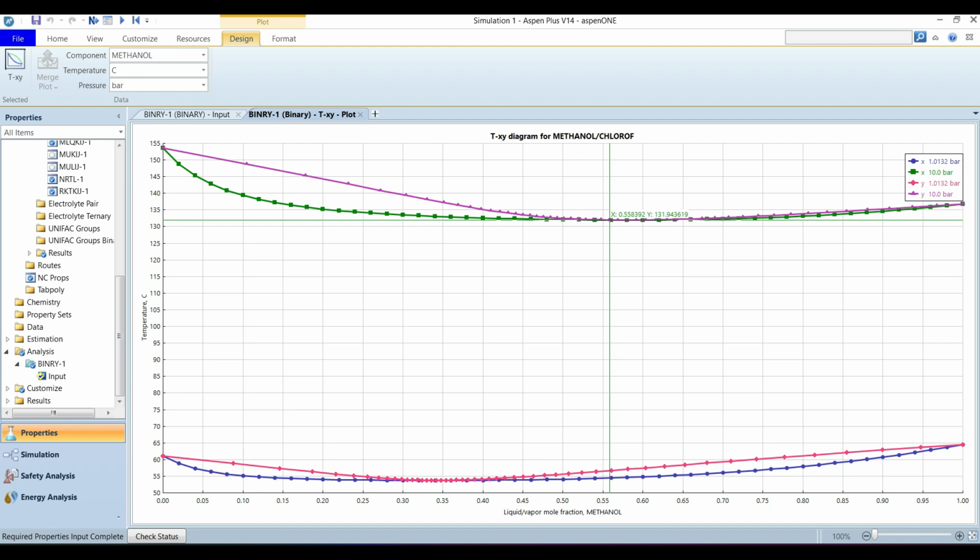So that will be a closed loop between the two columns, first operating at a lower pressure, then generating the pressure to a higher pressure. The second column will be operating at a higher pressure. When the products are obtained from the two reboilers as different products, then we can reduce the pressure from the second column and reintroduce it in the first column. So that gives a very conceptual scheme of playing with azeotropic mixtures to get the pure compositions, and this is what we term pressure swing distillation.